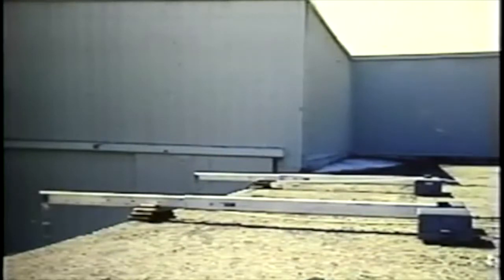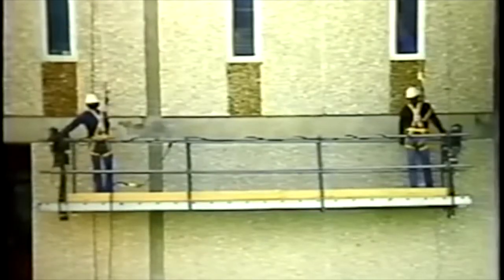2-point suspension scaffolds are designed for a total working load limit of 500 pounds, or a limit of 2 workers on a scaffold at one time. Due to the stress of constant movement by workers, the entire scaffold must be designed and capable of carrying 4 times the rated load. In addition, the supporting ropes or cables must be capable of supporting 6 times the rated load. All hoisting mechanisms must be approved by the Underwriters Laboratories or the Factory Mutual company.